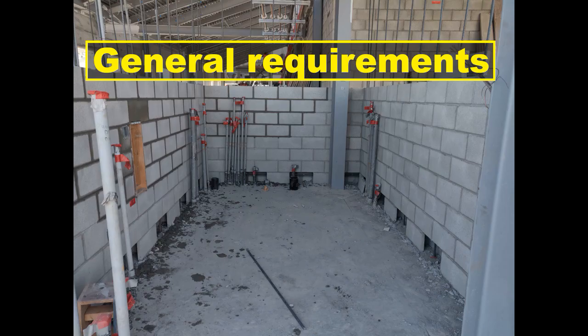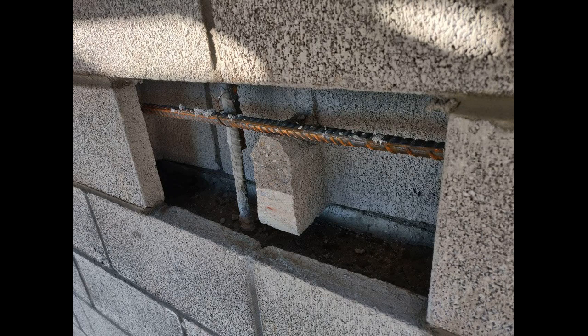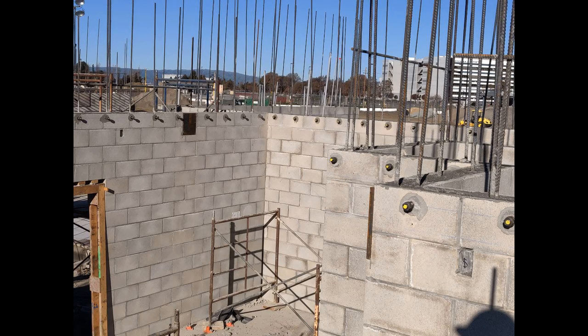General requirements. Do not change the source of materials, which will affect the appearance of the finished work, after the work has started except with building official approval. Submit test reports from an approved independent laboratory. Certify test reports on a previously tested material as the same materials as that proposed for use in this project. Submit certificates of compliance stating that the materials meet the specified requirements.